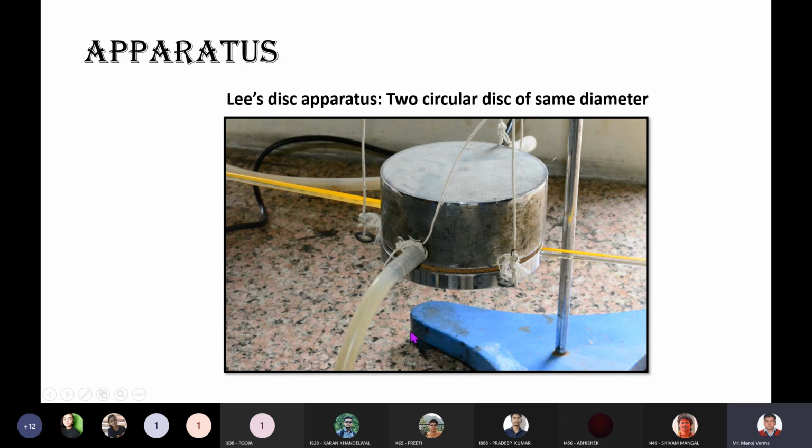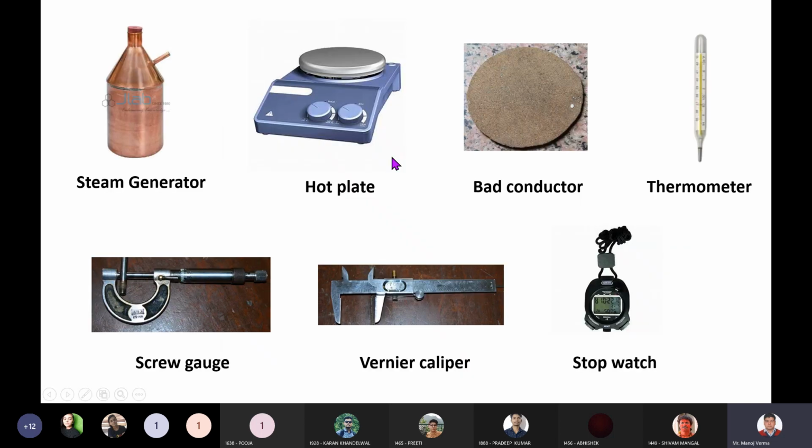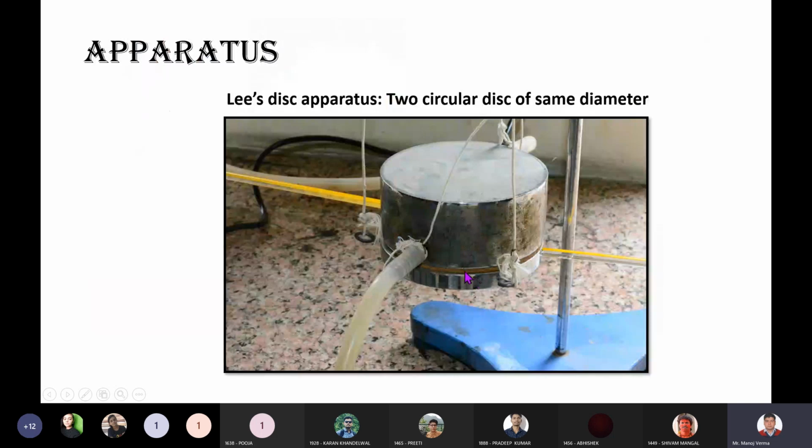And the amount of heat energy received by this slab B will start dissipating into the environment, into the neighborhood. It will start releasing heat into the air outside it. So a time will come at which the amount of heat energy traveling through this cardboard sheet downward towards slab B will be exactly equal to the amount of heat energy lost to the surroundings by this slab B, and that point is called thermal equilibrium.